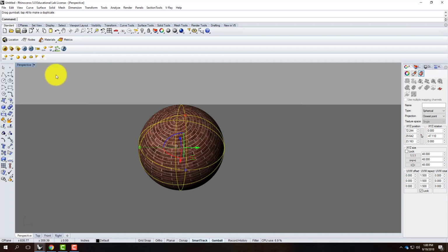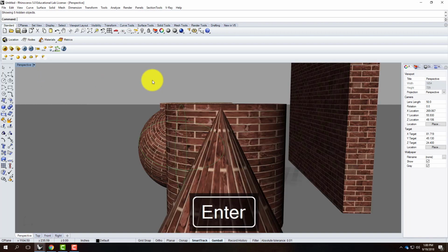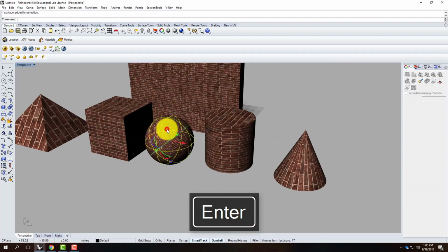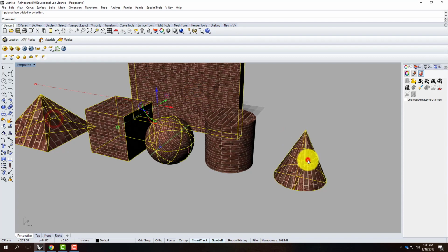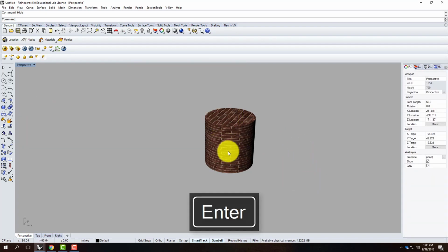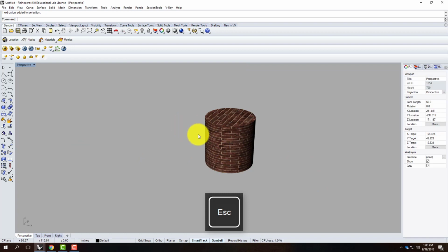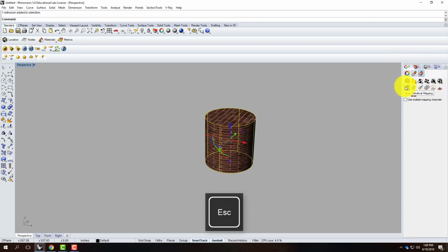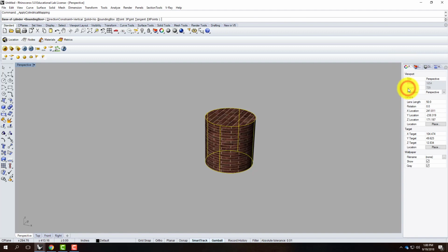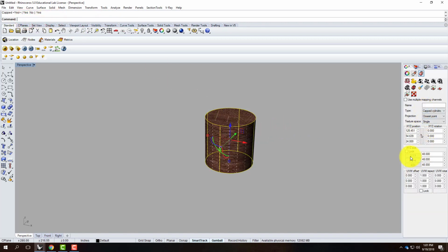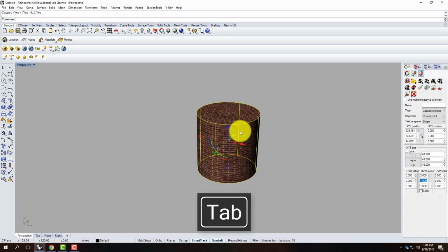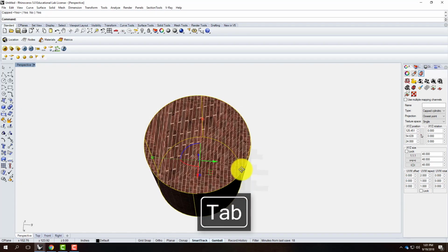All right, next thing I'm going to do, let me go to show, and we'll go ahead and hide. And we have just this object showing. So in this case, I bet you can tell where I'm going. There's a cylindrical mapping. I want to apply the cylindrical mapping to it. We can do a bounding box, world, and have it capped. And then we can control x equals y equals z. And we can control the repetition, probably closer to 2. And you can see it applied there.